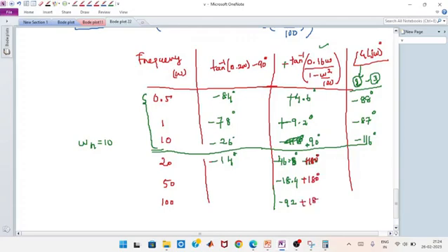Why? Because in a quadratic factor, the phase values vary from 0 to minus 180 degree, not 0 to 90 degree, remember. But our calculator has the provision to calculate values only from 0 to plus or minus 90 degree. In that case, you can't get the 180 degree case. For that purpose, I am adding 180 degree to each value after the natural frequency or corner frequency omega n. This is what I want to communicate to you, right?